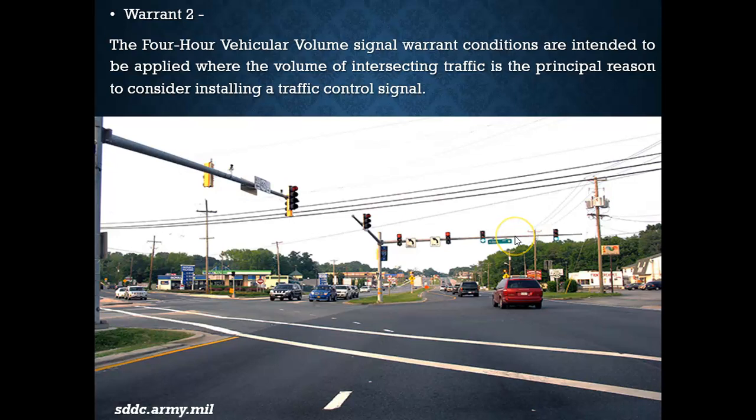Moving to warrant two. Warrant two is a 4-hour vehicular volume signal warrant. It is intended to be applied to know the volume of cars or vehicles plying a road at the point of intersection over a period of 4 hours.